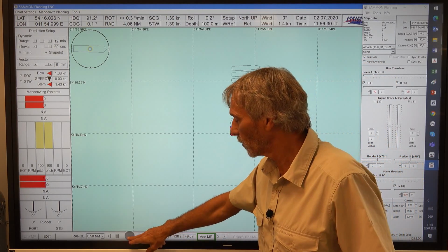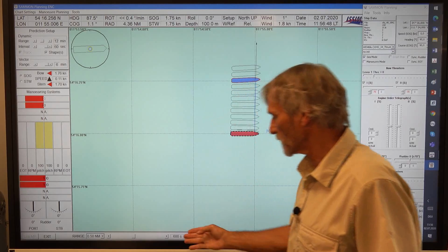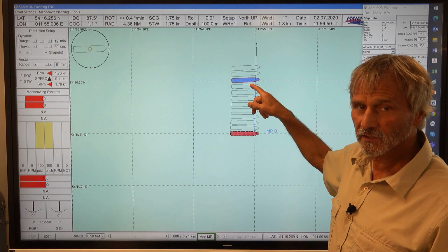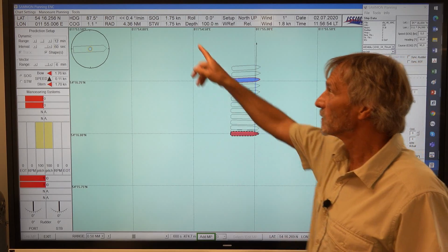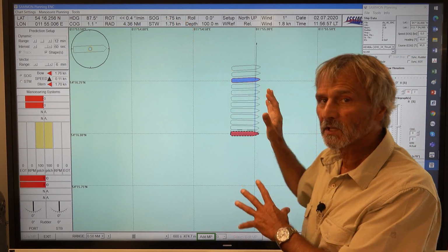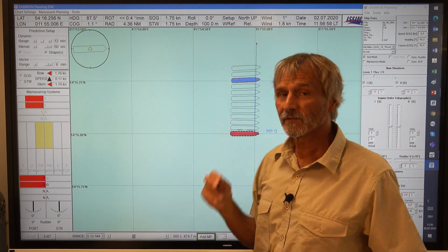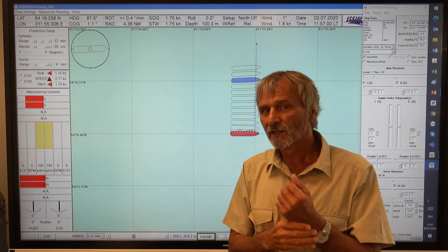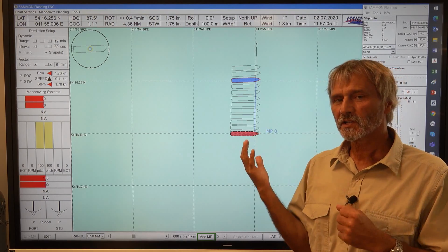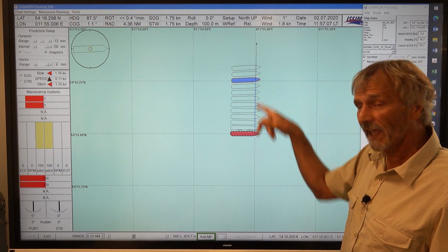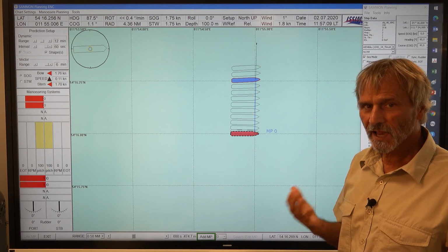And if we go further, so this is exactly 600 seconds. That means after 10 minutes we have been here. And the final drifting speed only by means of the thrusters is 1.75. So let's keep that in mind. This is without wind. So the question is now, can we stand also a high wind speed?